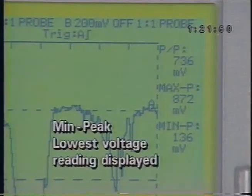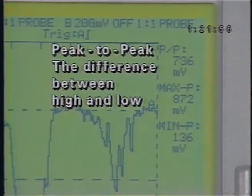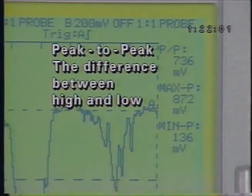Min peak gives you the lowest voltage reading displayed. Max peak gives you the highest voltage. Peak to peak shows you the difference between the highest and lowest voltage. That is, the range between the voltage peaks.